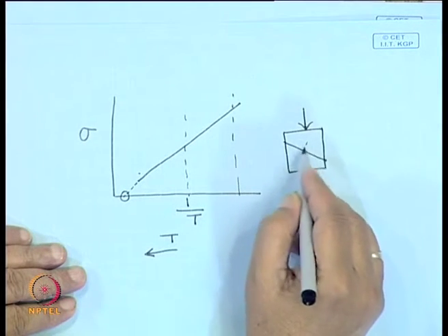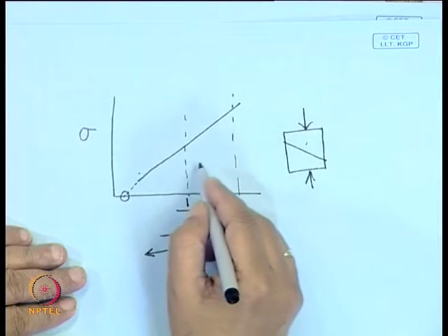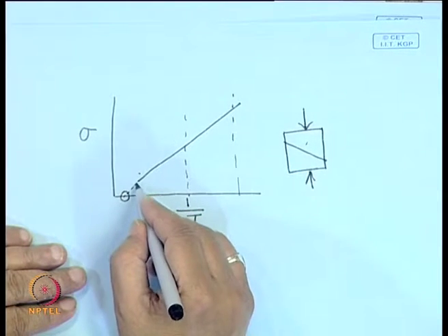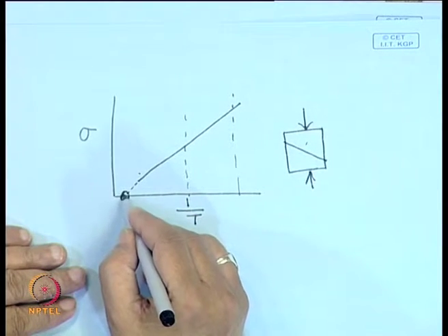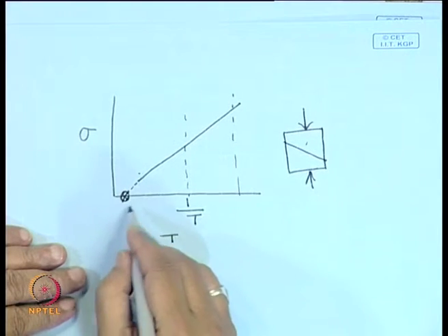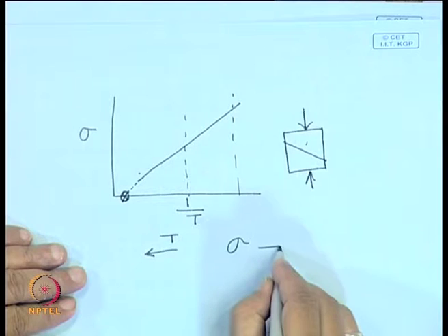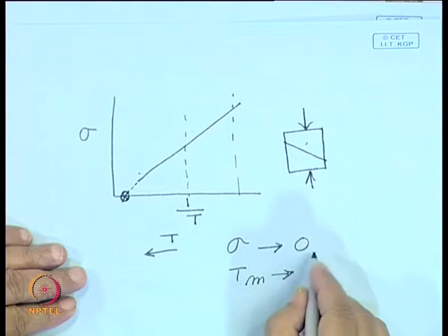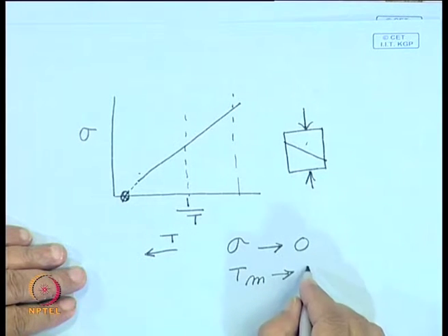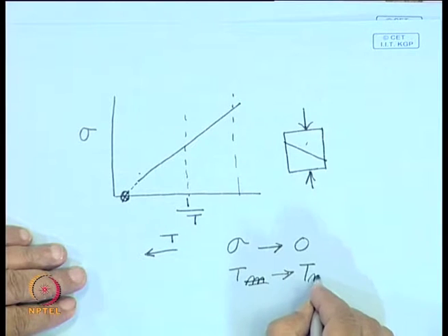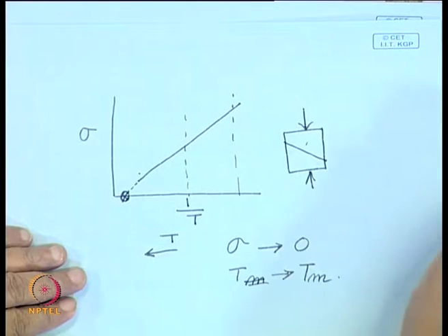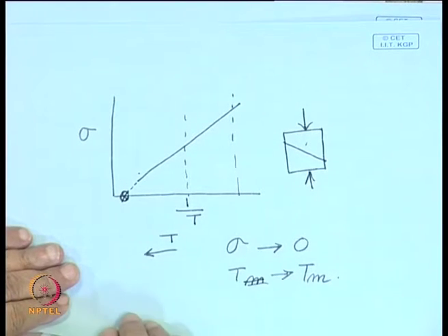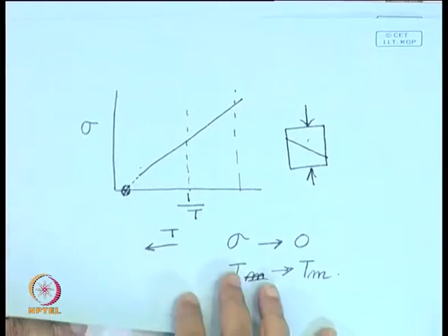Now metal has shear strength, but liquid does not. When it approaches the melting point, the material actually loses its shear strength. So, sometimes you will see that when T approaches the melting point, the strength of the material, or the shear strength, approaches 0. And in fact, most metal working temperatures are decided based on the melting point, or melting range, of the alloy.